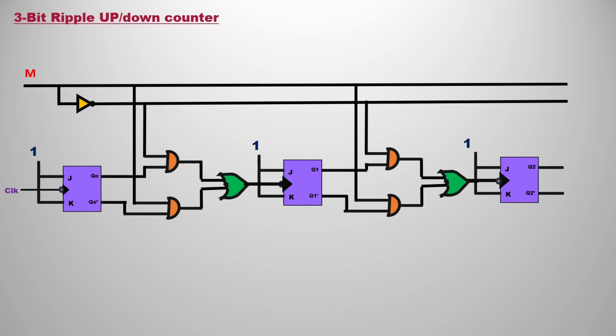In this one you have M and M bar, connected with two AND gates, and finally you join them with the OR gate. So this is the representation of a multiplexer. If you want more multiplexer videos, you can check out our playlist, where multiplexer videos are available. Otherwise, we can take the expanded truth table and derive this circuit diagram with the help of output expressions. But it's very simple to represent it as a 2 cross 1 multiplexer rather than remembering this whole circuitry.